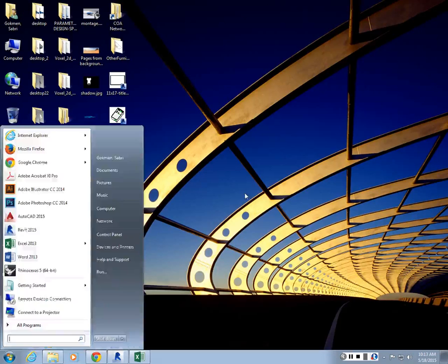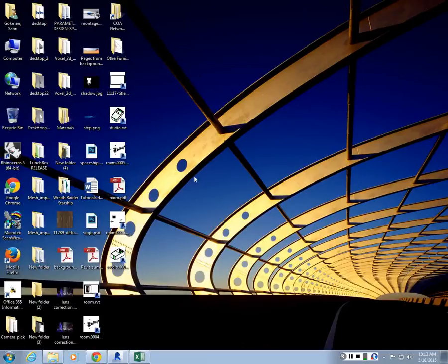Let's look into that. So I'll basically be covering some of the stuff from that tutorial. Well, if you do it in Rhino, all you have to do is just save it as a Revit file, and then... No, DWG. You won't be able to save a Revit file from Rhino. So you have to import DWG. Let's go over some of those.